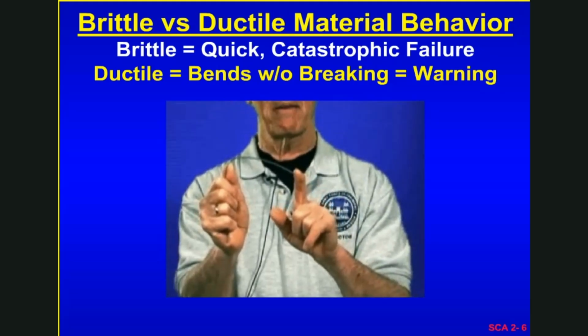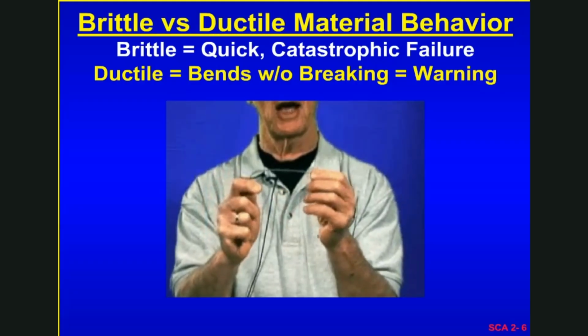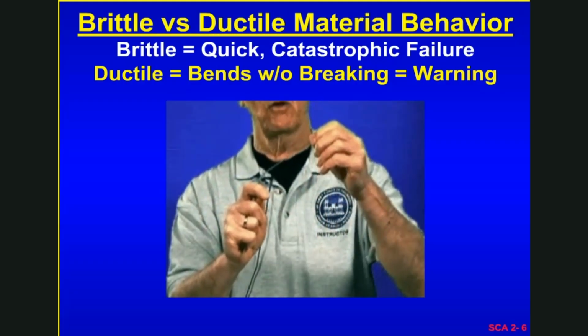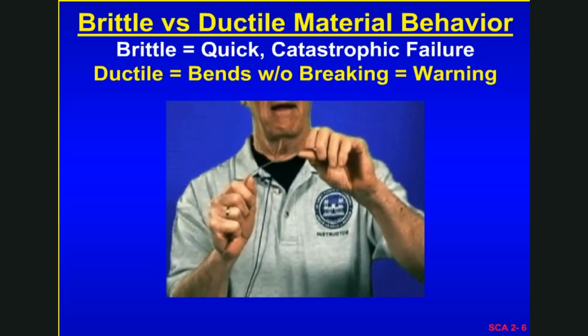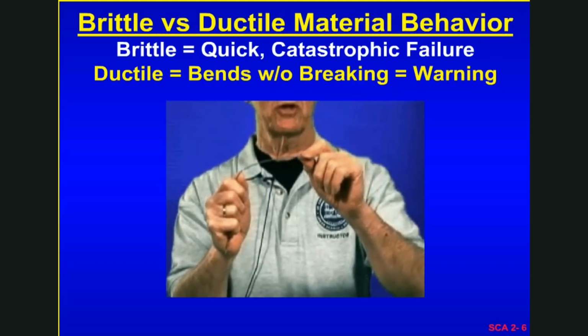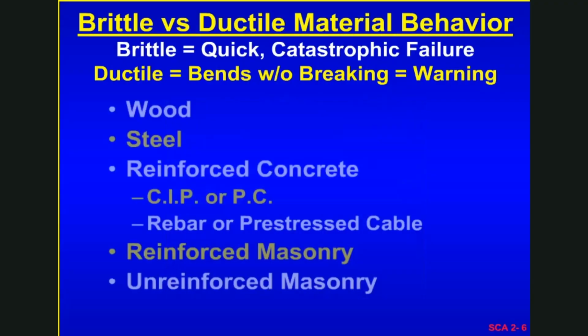You have to keep pushing on it to keep it bending, and you can reverse that force in the wire, and it'll bend back and forth, and that's how earthquake-resistant structures are designed, with lots of steel in them that will do this through the cycles of an earthquake.